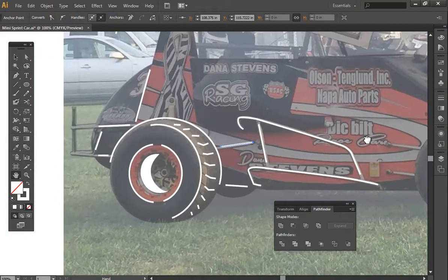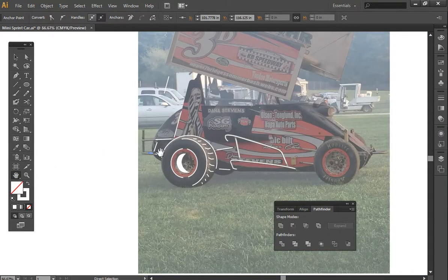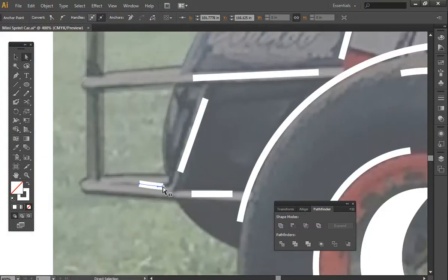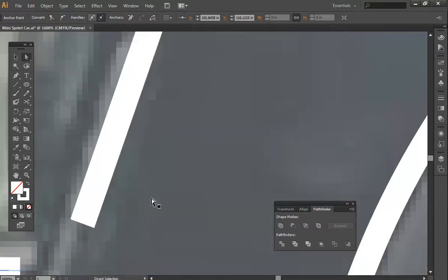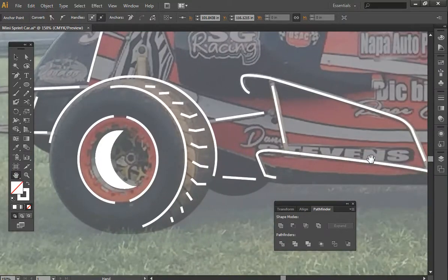So we have that, and I think we've got quite a bit. We can actually probably draw a little piece in here, something like that. Might be a little questionable right there. There's not a lot of metal that's around it, but I think with the values that I place in the artwork when I'm creating it, if somebody was to cut this with a fine tip consumable, this little piece of detail will actually show up without causing problems and having a piece drop off.